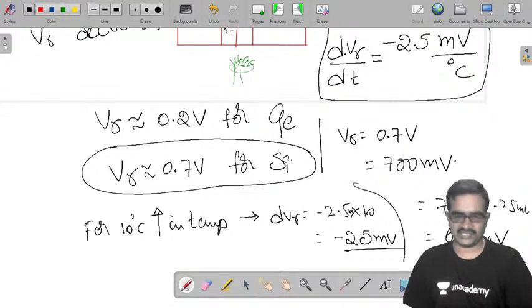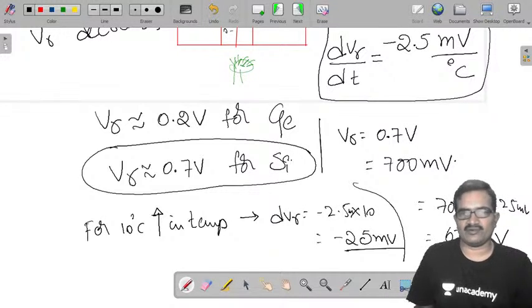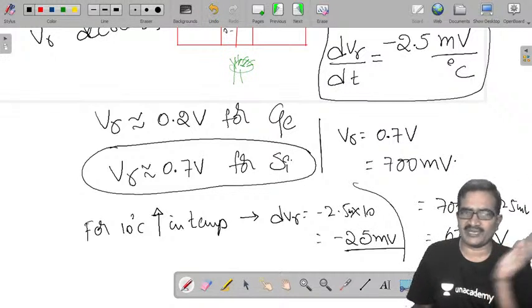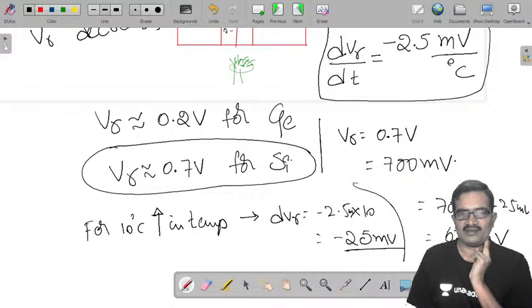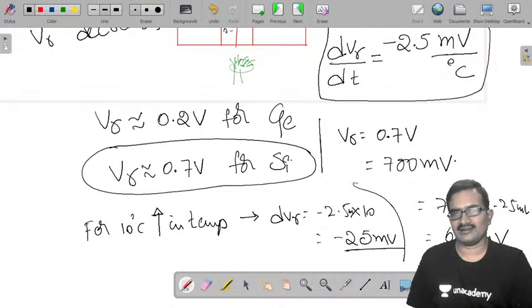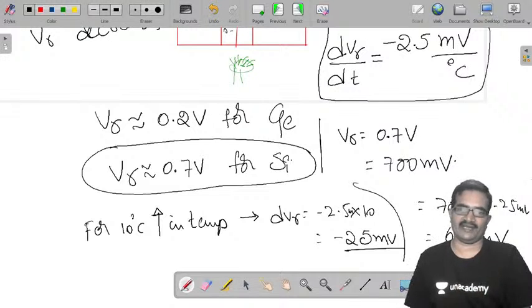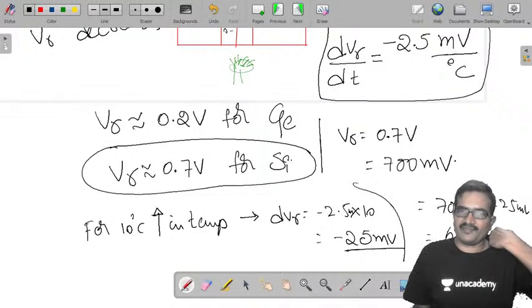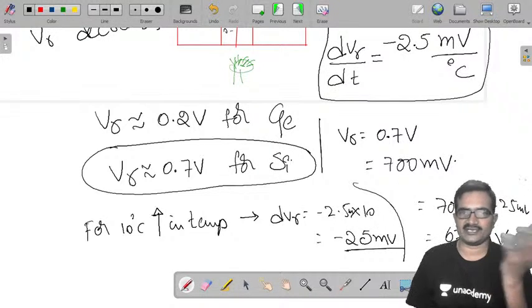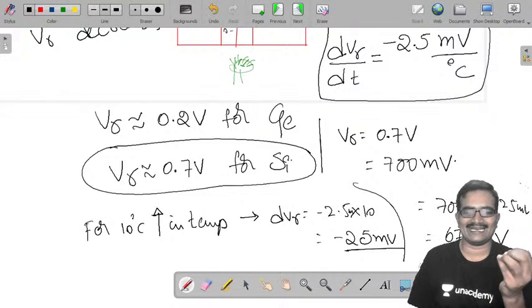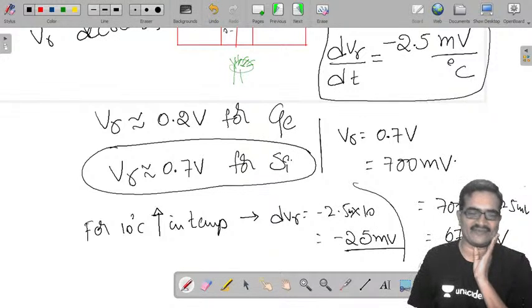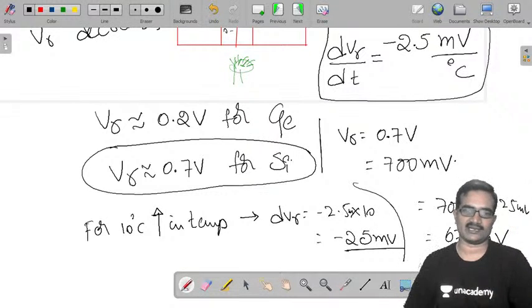So during the calculations, whatever values we are handling practically, 0.7 volts and 0.675 volts do not show much variation in the calculations, because there too we are taking e power Vd, e power the applied voltage. So there is an effect of temperature on Vγ, no doubt at all, but it does not have a considerable effect on Vγ. That is the conclusion.